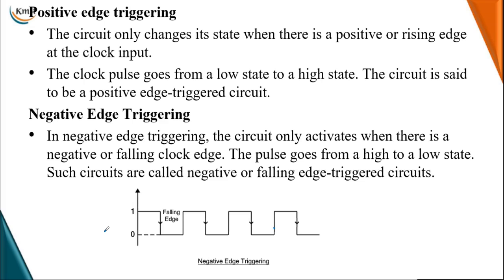And we have basic symbols in order to indicate that type of triggering. So now that type of triggering is here. I will note it down as positive level, which is indicated by the clock symbol with a sloping line. Then it is a positive level triggered flip-flop.